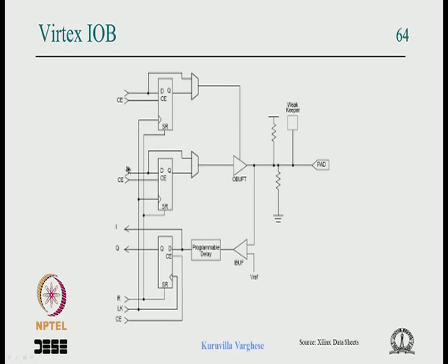Now all this can be combinational, it can come directly, it can go directly, and this enable path also can be combinational. But see, there are 2 things. We might get an input which is not synchronous with the clock here, so it can be input synchronized. We have seen the problem of metastability.